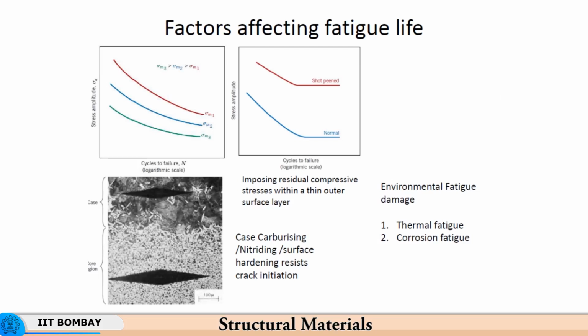On the case side there is very little deformation, on the core side there is a large amount of deformation, and therefore most of the damage gets accumulated at the interface between the case and the core. So the case thickness is something that is a matter of design.